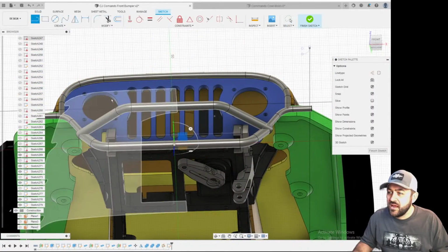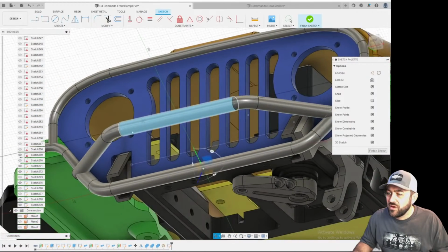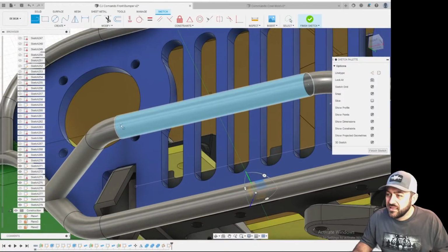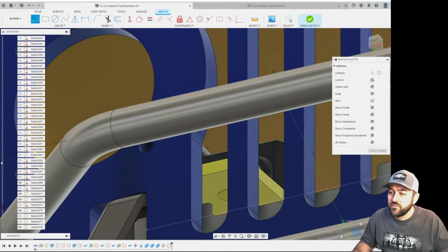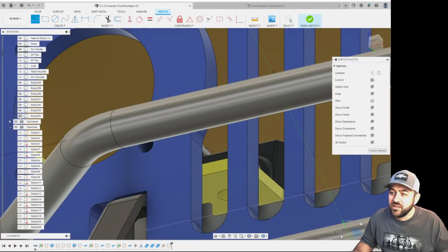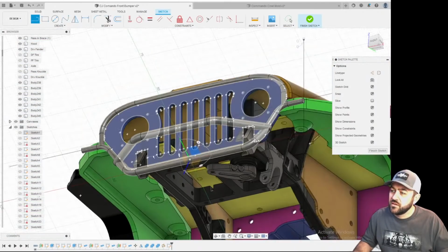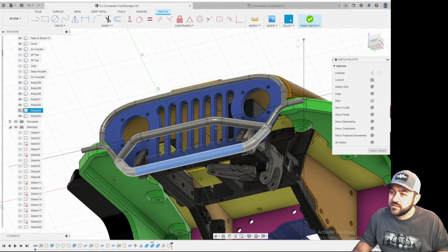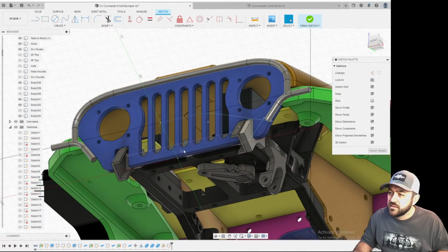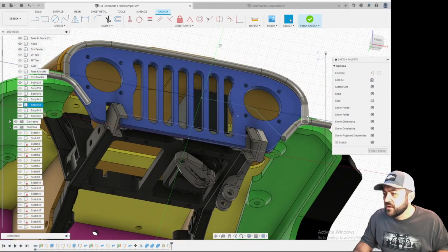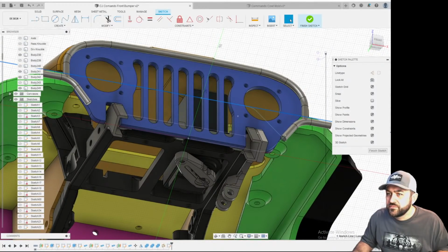So now for this, I probably will just want to keep it from being too difficult to fit this plate in there and then weld it while bending everything. First I'm going to turn off these bodies just because they're getting in the way of selecting the stuff that I want. I can probably turn off these sketches too, because we've already determined that we're far enough out.